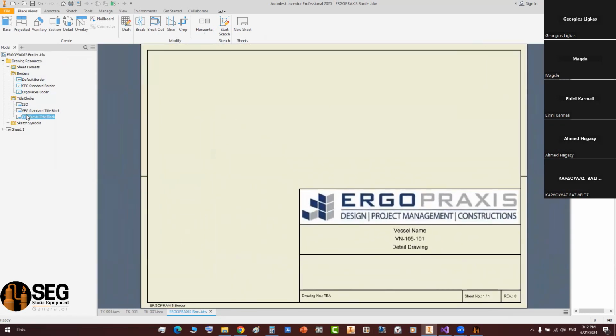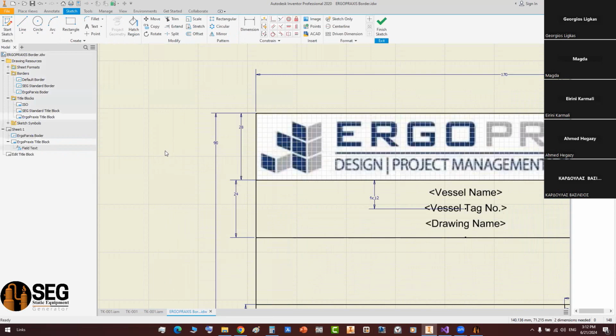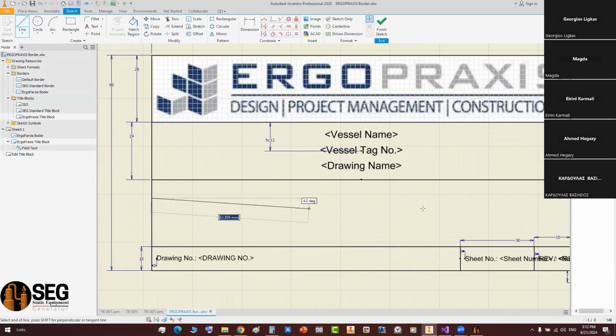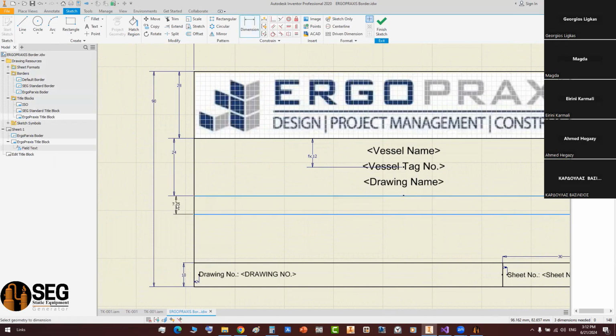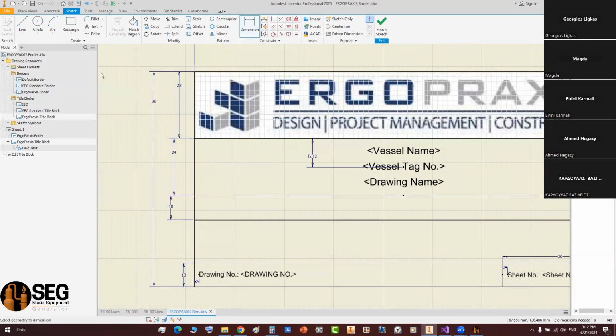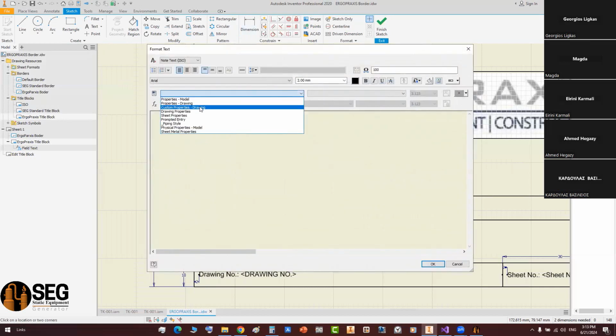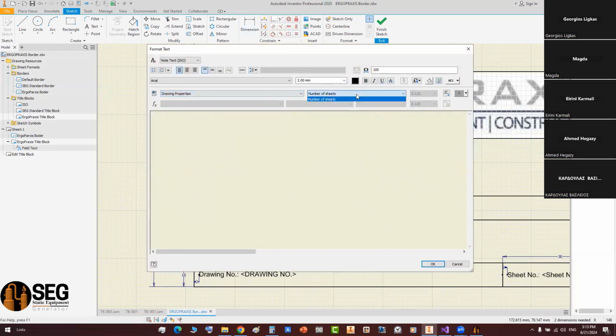Okay, well, let's add another parameter like the project location here and define that in millimeters. And from here, let's select the custom properties. Sorry, the custom drawing properties. And from here, you can add the manufacturer, location, part number, plant name, or project name. So let's add a project name.